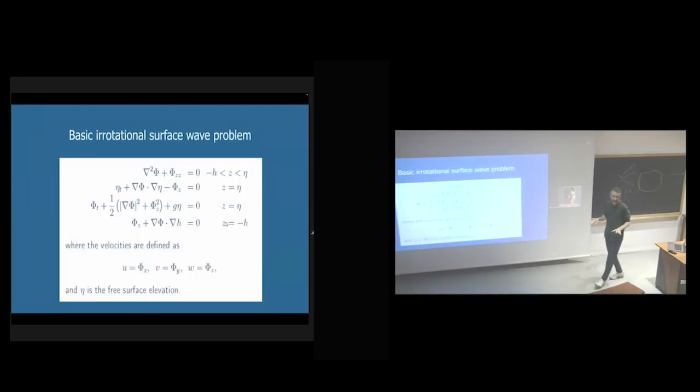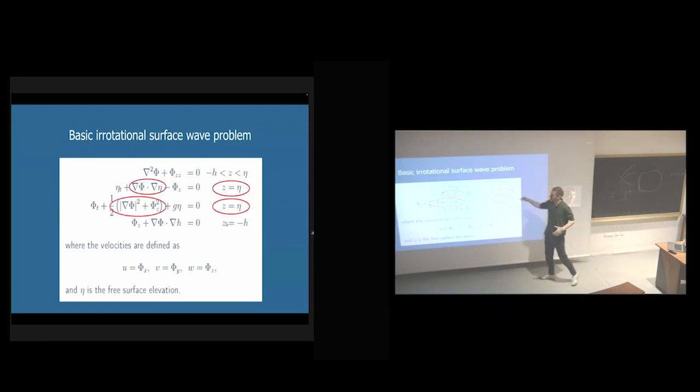I really took out most of the equations of this talk. These ones we know, yeah, it's a potential flow, and we have nonlinear components. Writing the kinematic and dynamic boundary conditions on the moving surface actually gives you an infinite nonlinearity series if you write it as a Taylor expansion.